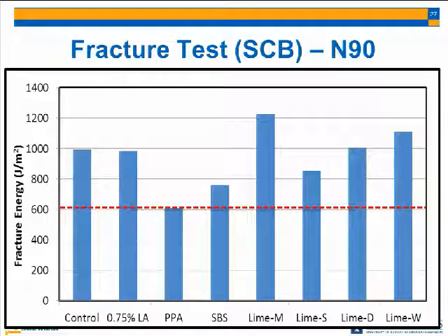Could it be compaction? 90 gyrations to 70 gyrations, but I cannot remove that effect. Yeah. Maybe if you had on your graphs the asphalt content, and then for each specimen, you'd probably want to put your density or something. Right. That way we can read that. Okay. Because maybe there's something there, maybe there's not, I don't know.